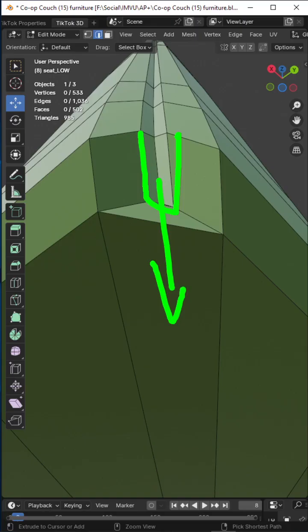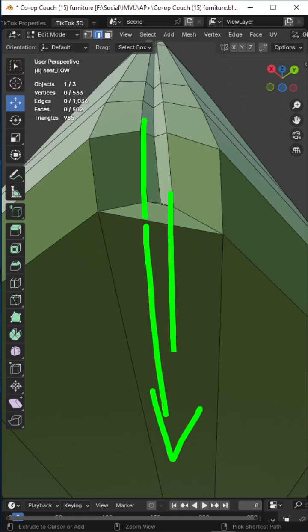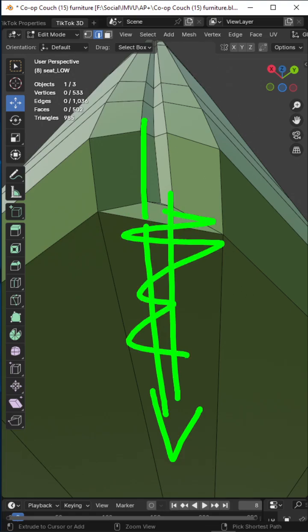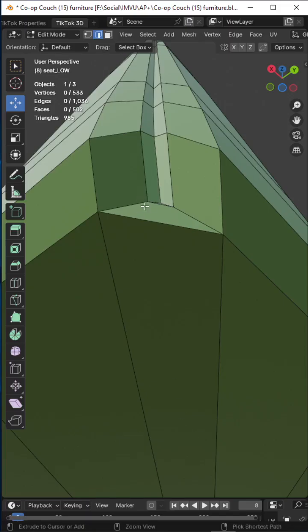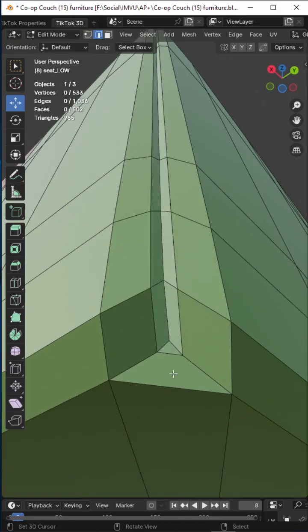We don't need to worry too much about that because we're going to eventually bake normal maps, and the normal map of the high res has this continue under the chair. So when we texture this, we can take advantage of that, so we can leave this relatively flat and unstructured, or well, undetailed, and it'll be the normal map that does all the work in terms of how the object appears in game. So we're creating the illusion that this detail continues because of the normal map versus the actual flat structure.